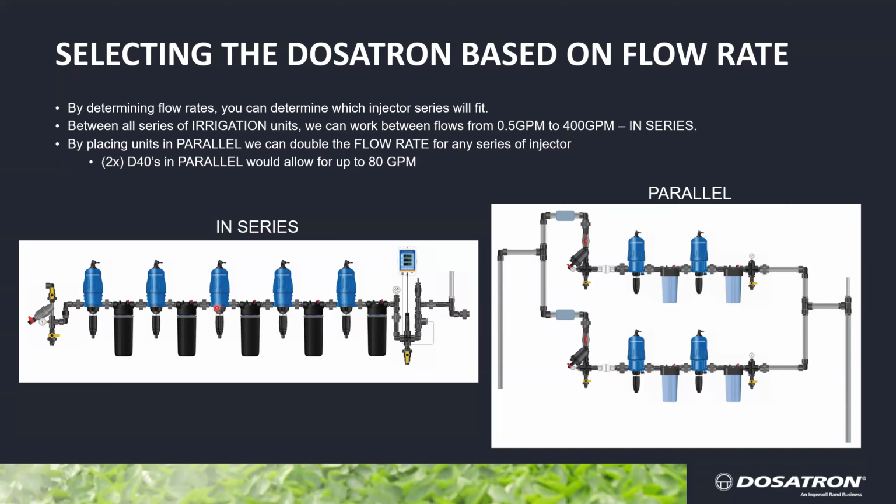The other way that we can use Dosatron, and this is to double our flow rate, is we do a system that we call parallel. So by placing units in parallel, we can double the flow rate for any series of injector.